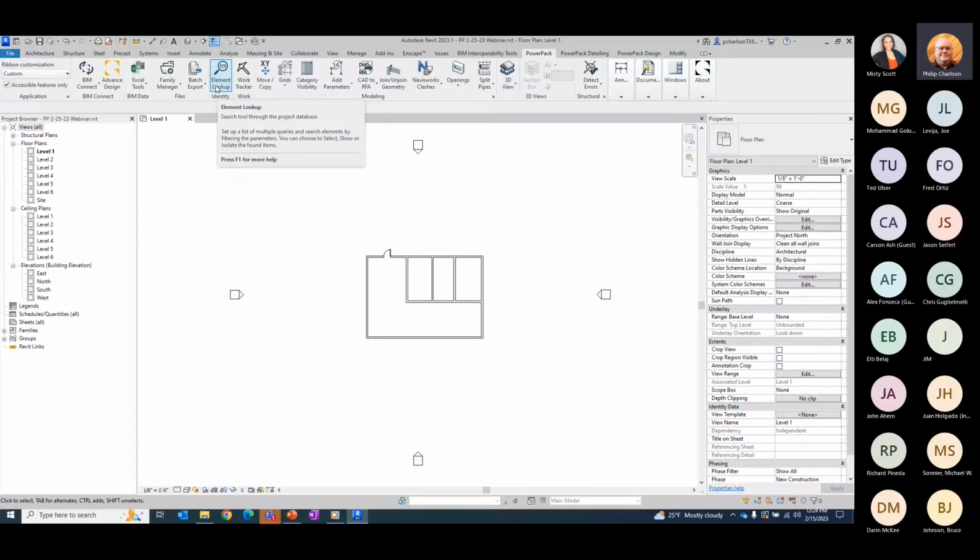It allows you to go in and select it, and it could be multiple items, many elements within that selection. And then you can go in and obviously modify just those components. So a nice tool to really be able to find items within a project. So a little bit different than just simply using a filter with the out of the box Revit. With that, you just kind of window select and whatever you have highlighted, that's what you have as far as your lookup items for a filter. But this is going to look up everything within your entire project.